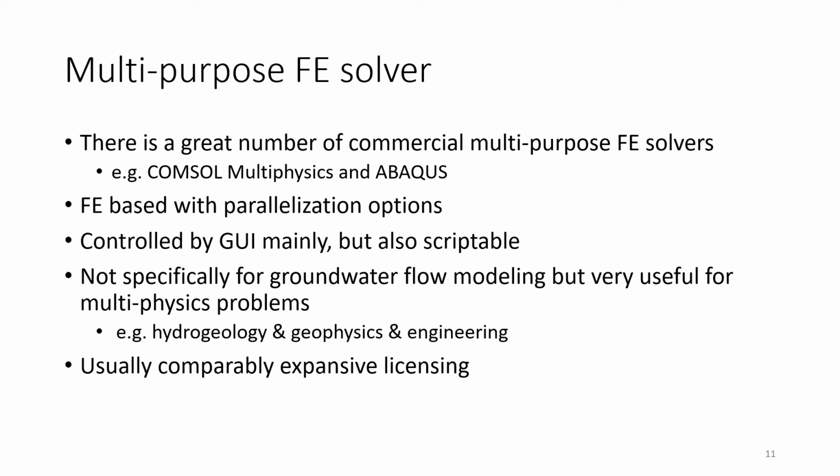So for example, if you want to couple groundwater flow with geophysical exploration, so you want to know how, I don't know, the electric resistivity of the subsurface changes based on different groundwater conditions, then you will have a hard time modeling that with VFlow, or I don't think even with OpenGeoSys, for example, but then COMSOL would be the choice, because it can simulate in one package the groundwater flow and calculate whatever else on electric fields using another package. So there is, you know, a lot of things possible here, and depending on, for example, the company you're hiring, it might be that they have a COMSOL license because they need it for some other applications, and you can also use it for groundwater flow, right? So it's not specifically designed, so it doesn't have, as I said, some of the user convenience which Spring or VFlow has, in terms of putting observation points and getting these breakthrough curves for tracer tests and stuff like that.